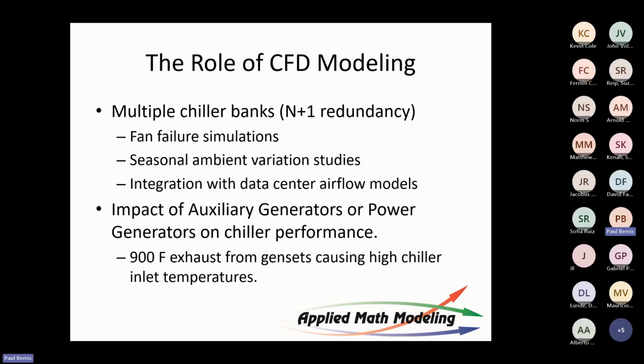So you've got to include cooling the fans of the air handlers. You've got to include the compressors if there are any. You've got to include, of course, the loads of the individual racks. That's going to be the amount of heat you have to dump. Then use that as a baseline criteria for determining how many chillers you need and where they're going to be.